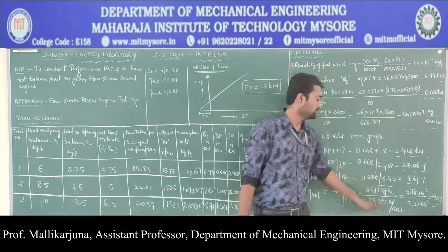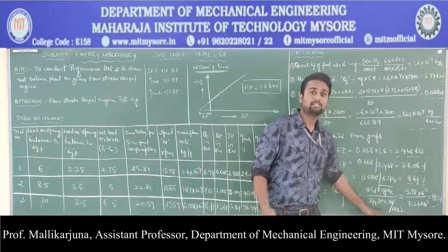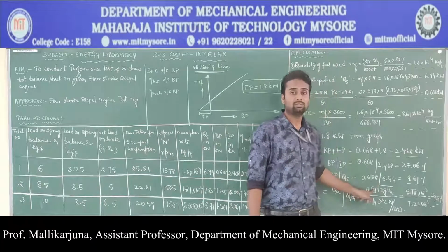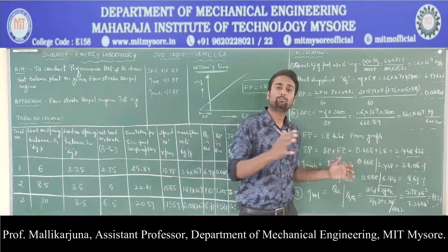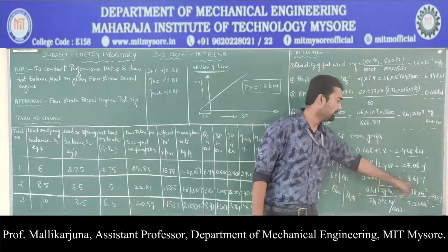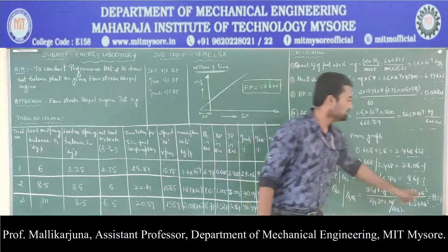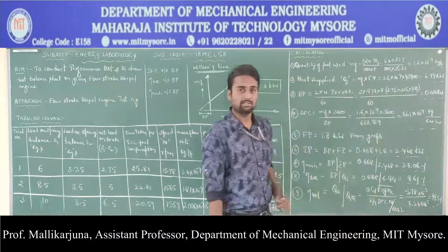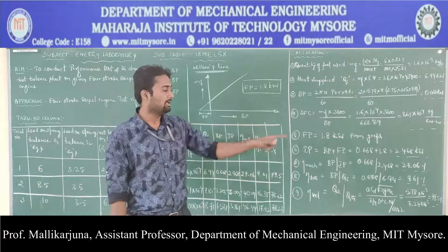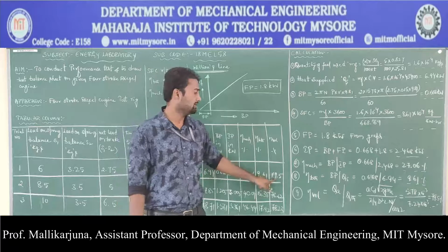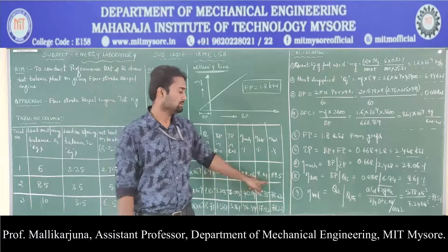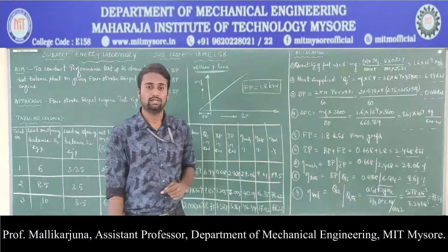So this becomes the theoretical discharge that can accumulate inside the engine cylinder, and this is the actual discharge from the orifice to the engine. If we divide these two values, we get a volumetric efficiency of 79.5%. In the sense, among 100% availability of the volume of the engine cylinder, 79.5% of the volume is filled with air. That is what volumetric efficiency is saying.